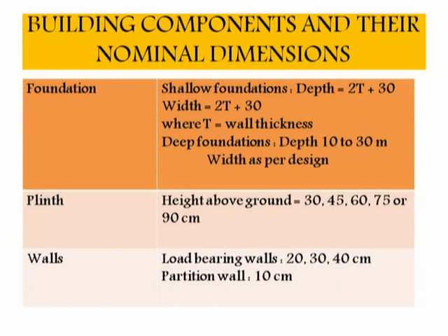So in a 45 cm plinth there will be 3 risers. In a 60 cm plinth there will be 4 risers. In 75 it will be 5, and in 90 it will be 6 risers of the steps included in that height of the plinth.